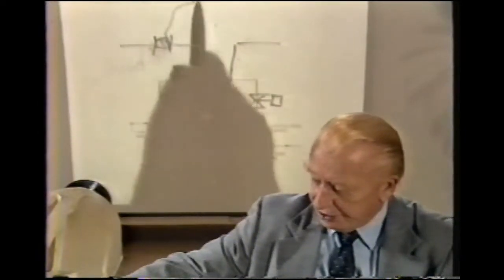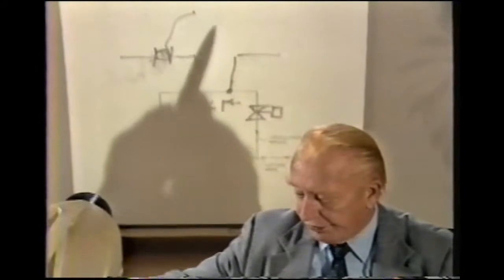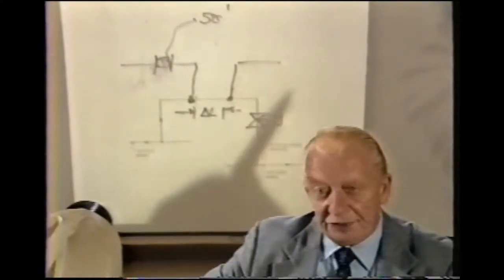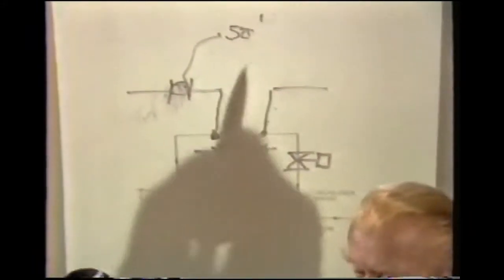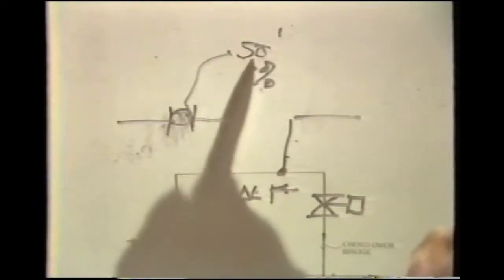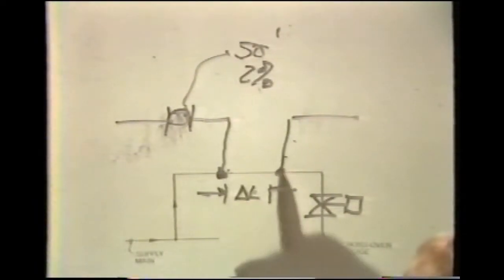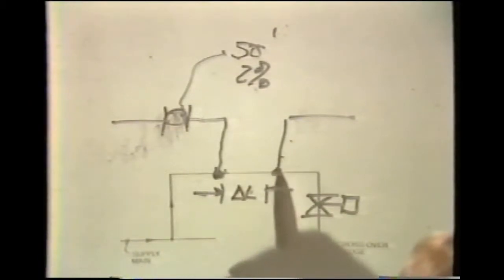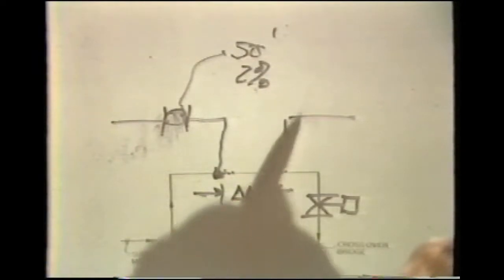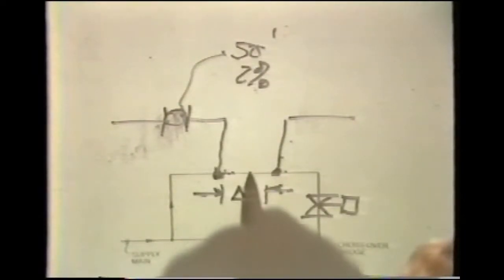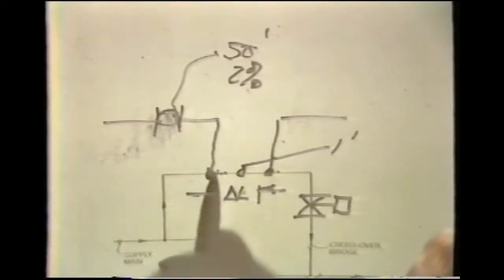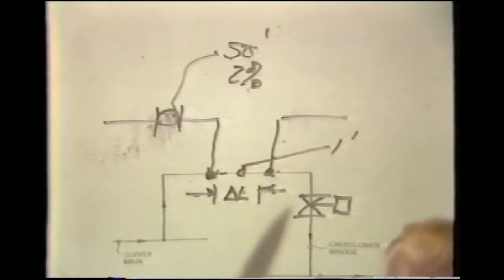And we can assess that if a pump has a head to the order of 50 feet, as an example, that we can utilize about 2% of that head as the head developed across the crossover bridge. Now, this would mean that we could, for this circumstance then, allow about a 1 foot head loss in that common piping.